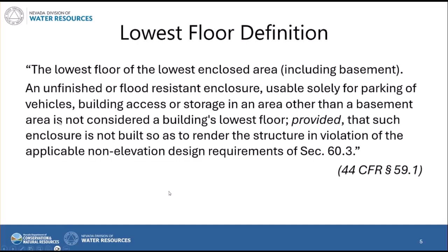And what do we mean by the lowest floor? Well, the NFIP defines the lowest floor in the Code of Federal Regulations in this very long and convoluted way. It says the lowest floor is the lowest floor of the lowest enclosed area, including basement. And then it goes on to provide some exceptions.